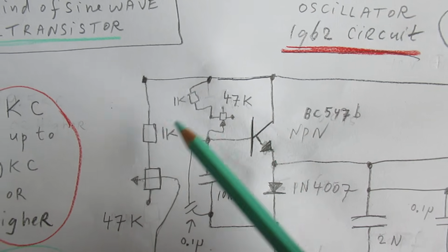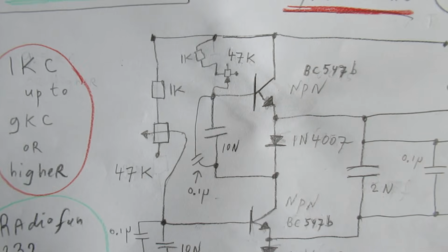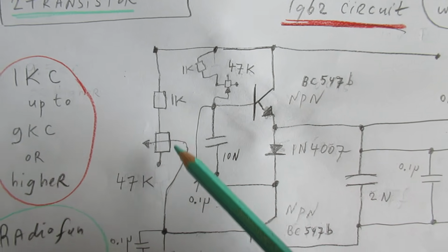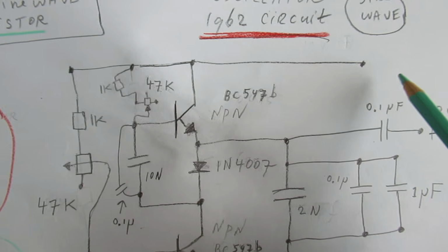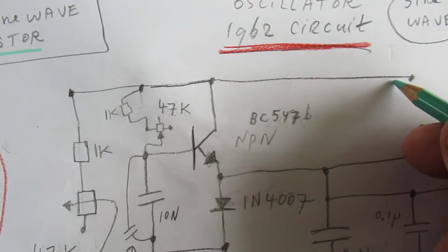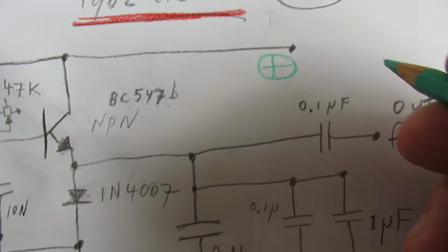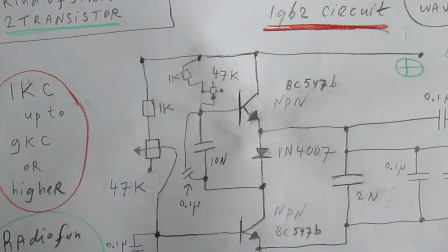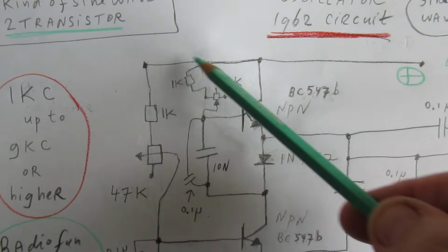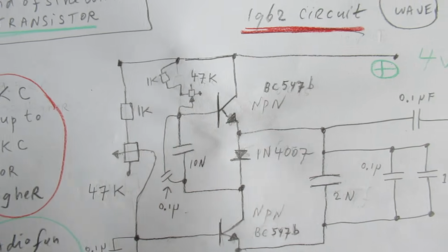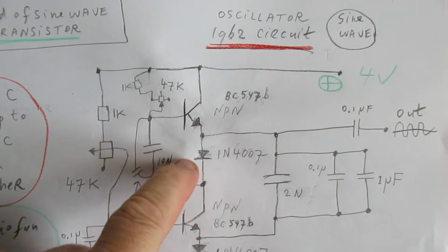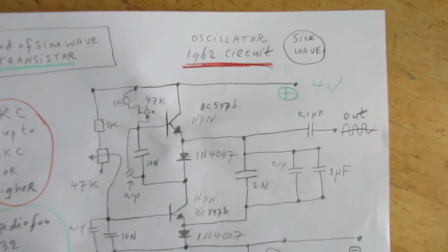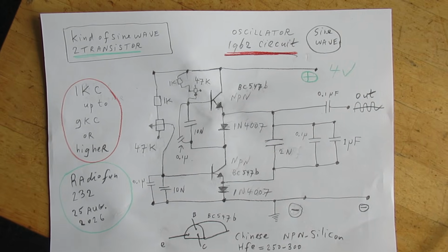And this is the protective resistor, 1 kilo ohm, always very important. When it is not there and you turn here the wiper to say the positive lead, this must be positive here in the order of 4 volt. When you do that, the transistor will die immediately because of a too high base current, and the same applies to that other transistor. That's the reason why you have here a protective resistor and also here. Schematic again.